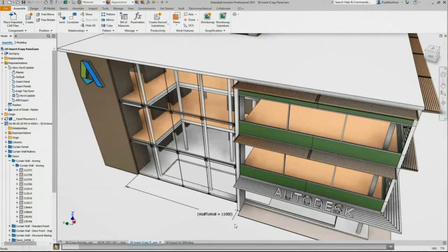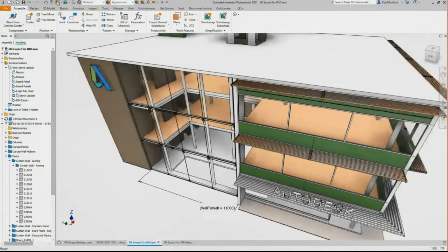Now, in a vaulted scenario, we would receive the updated model through Vault's use of the project sync with BIM 360. So we'll only know that there's an update needed once we receive the updated model in Vault. In Inventor, we'll click on the Update tool to update the referenced Revit model.